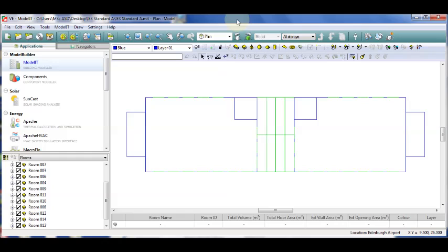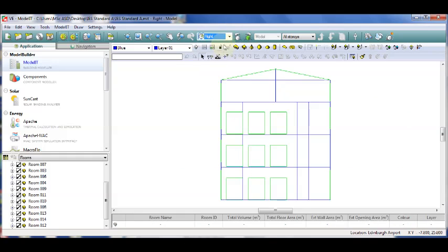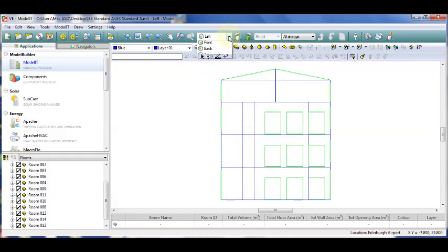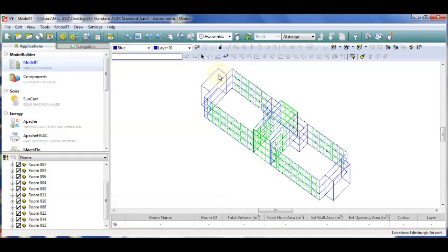So when you open up your model, you're going to see a screen like this. This is the IES Virtual Environment, which is currently showing on its main window a plan of a wireframe model of what was imported. Now you can't really tell much about that. You can only see it's a plan because of this box up here. You can change the view of what you're looking at to elevations, but probably most obviously to axonometric, which is that one there. Just to highlight, here are some various tools that you can edit and add things.